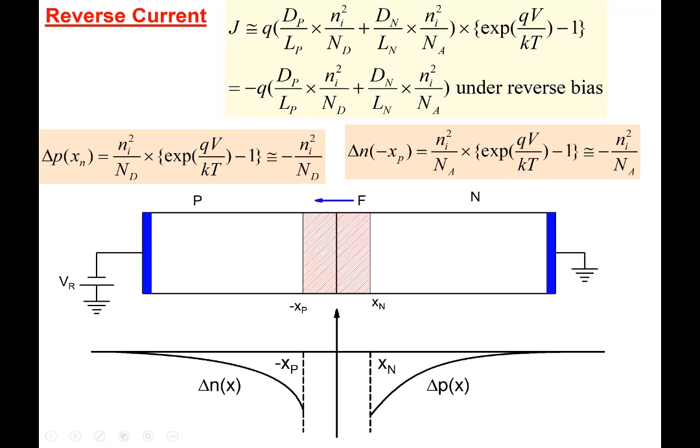So this is what is happening here. It goes like this, just the opposite of earlier, when we had excess carriers here. Now we don't have excess carriers; we actually have much less than in the bulk. At this edge, you have extremely small numbers of carriers, practically zero. What is the number of carriers far away? Ni square over Nd. So what is going to happen?